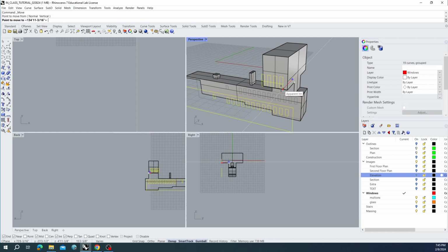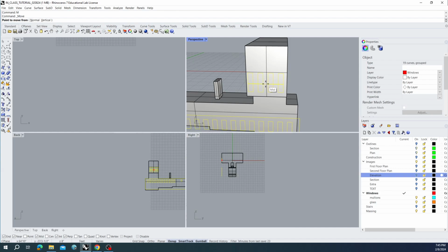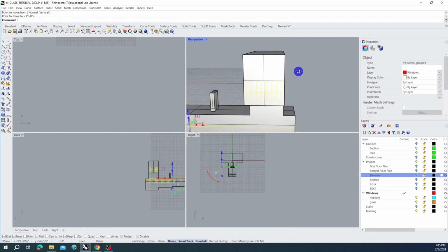As we know, this building is very symmetrical. So another way that we can double check some things, maybe in a way that our plans and elevations don't line up properly. We know that these windows are centered on this facade. I can use that previous midpoint from my mullion guideline, line it up with the midpoint of this elevation.